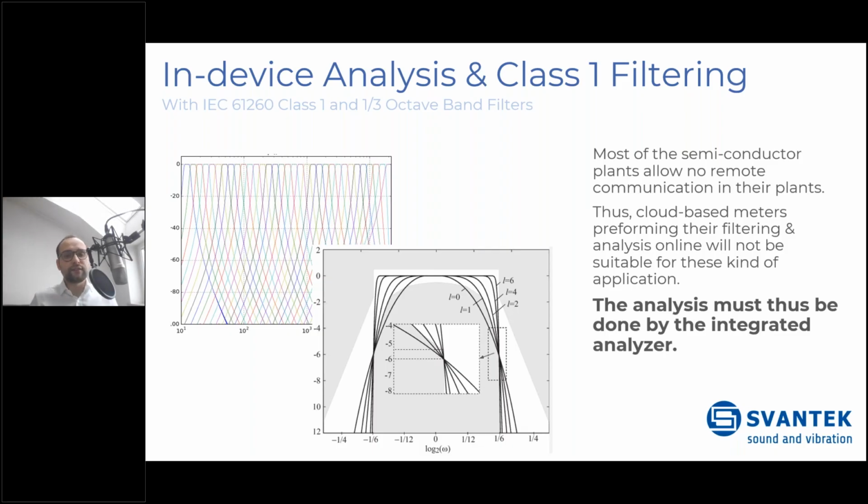We all know that when performing the FFT, we can choose everything from the windowing functions, from bin sizes, from overlappings, etc. All of that will affect the way the result will look, even though the time signal is the same.